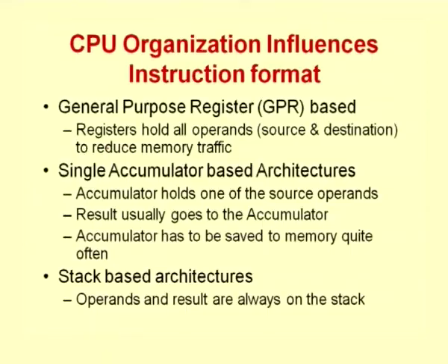The third type of architecture that we talk about is the stack based architecture. In stack based architectures, there are no registers, and all operands and the result are always on the stack. Everything is maintained on the stack. You will have an ALU, but all the data to be operated on is on the stack. You have to bring data from the stack to the ALU, perform the operation here and store the result back into the stack.